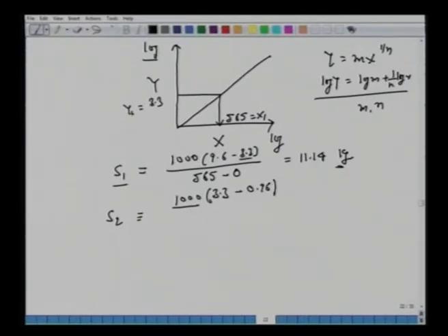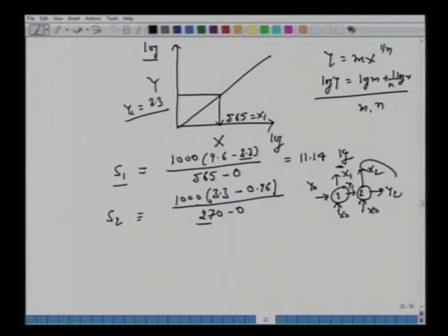So that's why we said this y1 is an intermediate variable. Divide by, now look at this, we should have 270 minus 0. So what is this 270? Go back to the schematics, stage 1 and stage 2, with x0, y0, and x1 and y1 in equilibrium. Similarly we have y2 and x2 in equilibrium. So if we know y2, which is 0.96, we can go back to this curve. Here this is 0.96. Read from the graph, we should be able to read this number as 270.